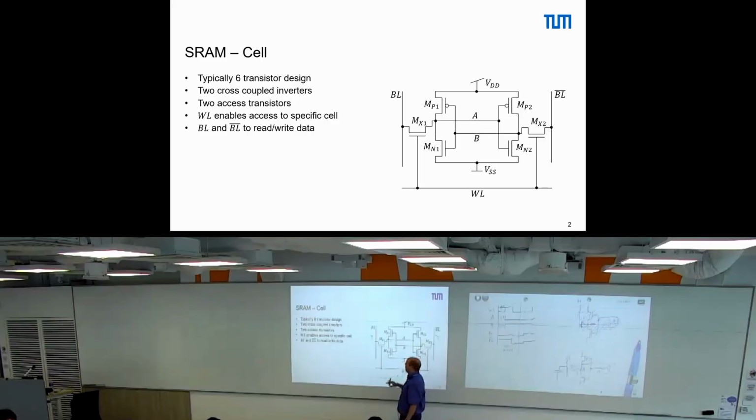current 1. And if we preload, what we do is actually we preload here with a large capacitance. If we preload this large enough, then we will first put this towards VDD half, put this here, same effect towards VDD half. And then, depending on how the internal structure is and so on, this will either flip to 1 or 0. Because you have an inverter, it should go at some point into a stable state, if you wait for long enough.